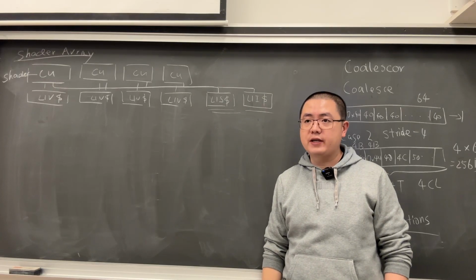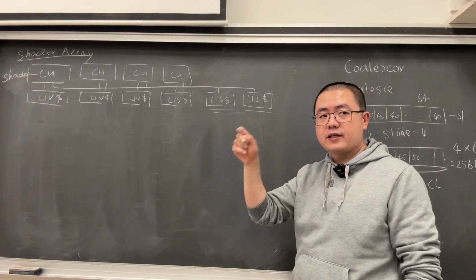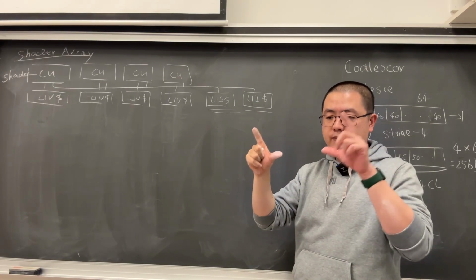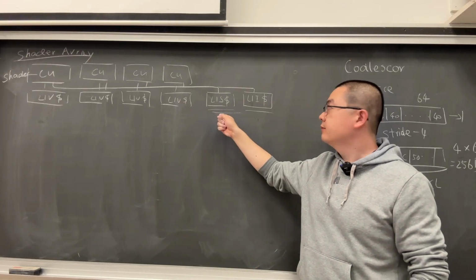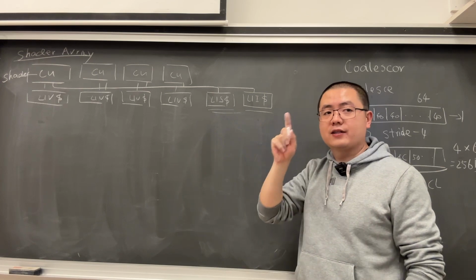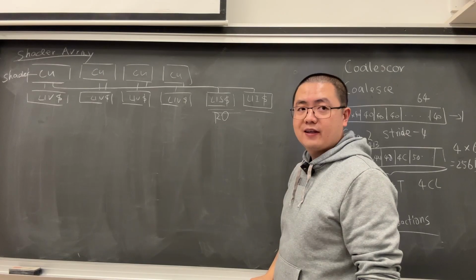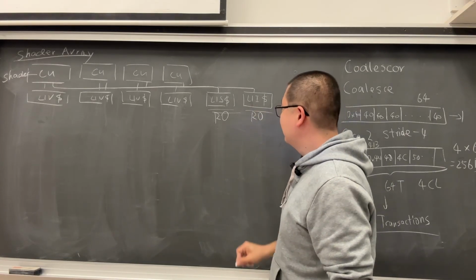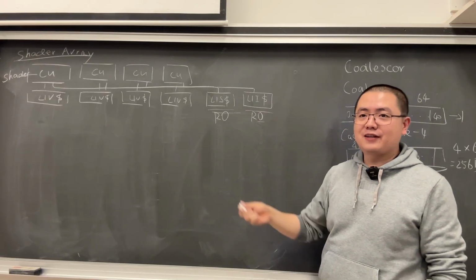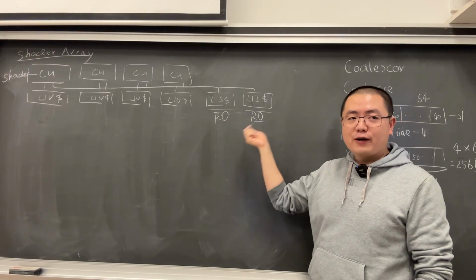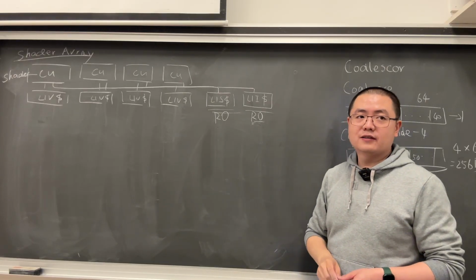Scalar is also the same idea. What does scalar memory do? By the way, scalar memory is the responsibility of the scalar unit. It can also generate some load requests into L1S. No write, only read. This is read only. It's actually not exactly read only, but you can consider it read only. Why would we need to write into the instruction cache, right? But it's not important. Just consider this a read only cache.